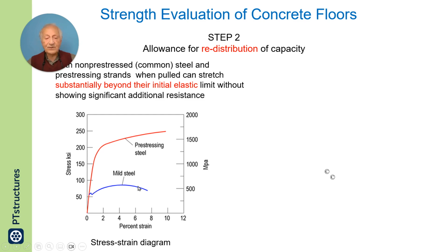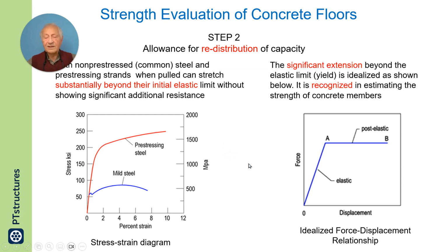This is conventionally rebar, and this is post-tensioning. This deformation without increase in resistance can be utilized in redistributing the force to places where resistance is available.